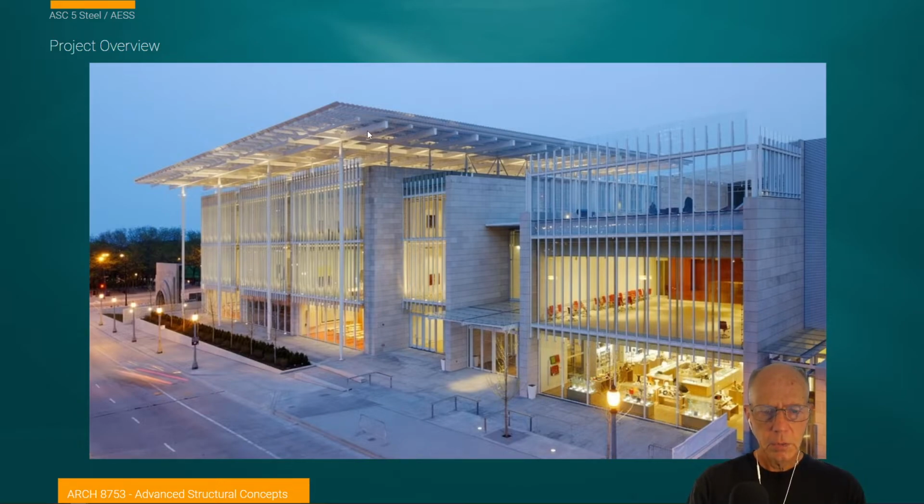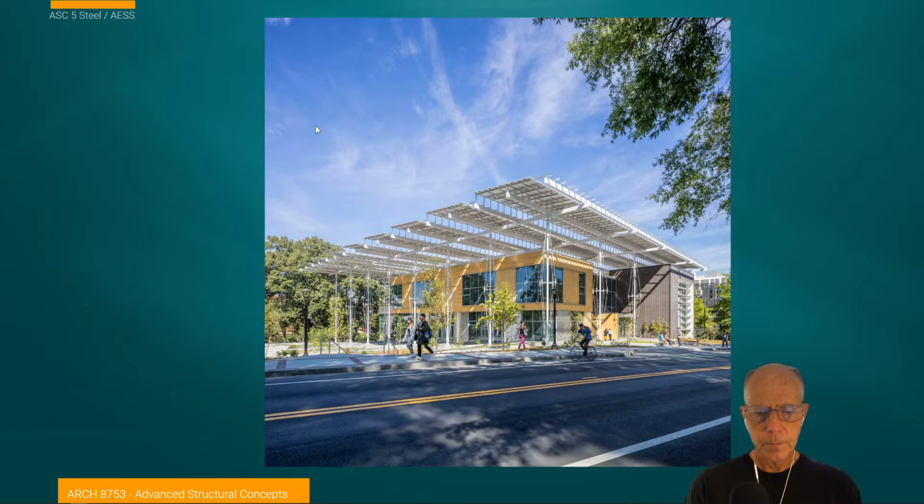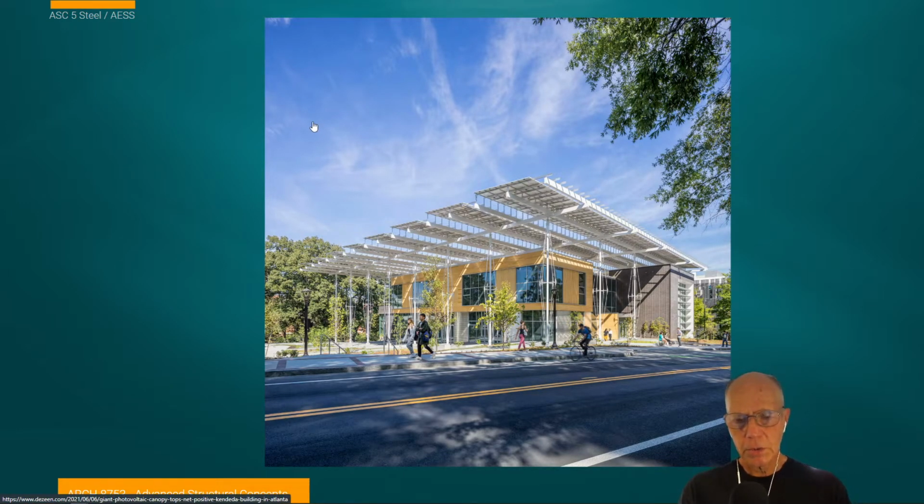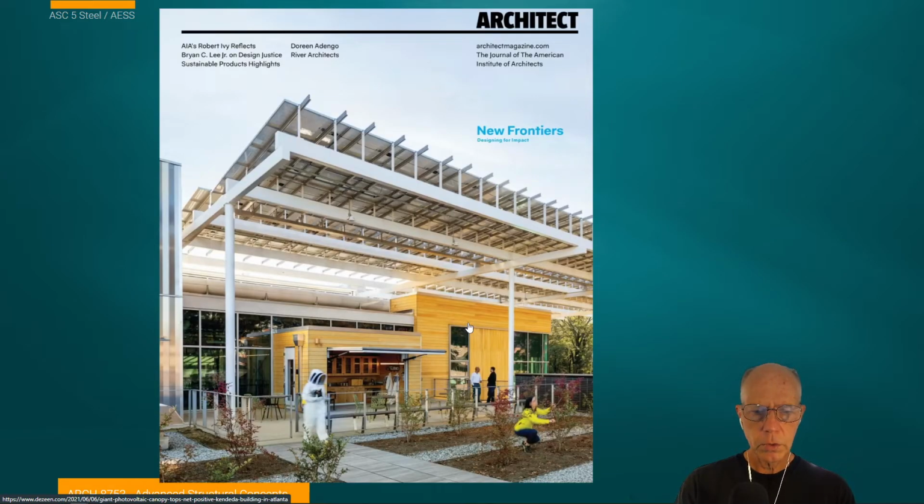So when we get to this last column that's supported, these outrigger columns are much thinner because they're carrying less tributary load. I hope you're motivated to think through this project, because I'm showing you this image since it's a very common technique used today, especially when we're trying to float photovoltaic arrays around. Many times we don't even have enough room on the rooftop for the amount of capacity. The attendant advantage in many climates for these kinds of structures is to create a cooler, shaded, protected area around the building, which can help with energy load and cooling requirements.